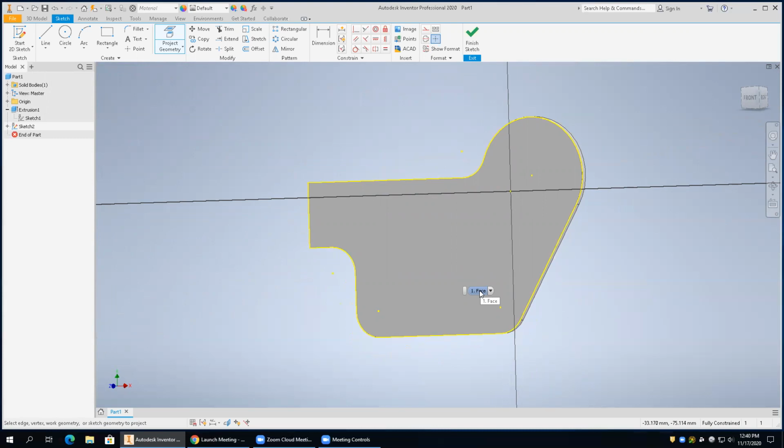You actually don't have to go into the jointed, Kevin. Did you get a project geometry? You've got to go up to, oh, okay, you're not in a sketch. You've got to go into the sketch. Select your top surface. Okay, now we're going to do a project geometry. Just get here, it should project geometry. See the yellow? Yeah, you're good. Anybody else okay? So you took the geometry and you moved it up, okay, so that we can work with it.